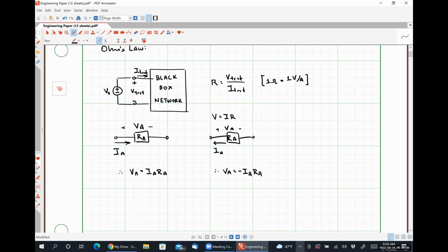Okay, so these relationships effectively force a resistor to always be absorbing power and energy. So if the current is negative, the voltage has to be negative as well, so that the product of those two things is always a positive quantity. And again, that is purely because resistors are incapable of storing energy.